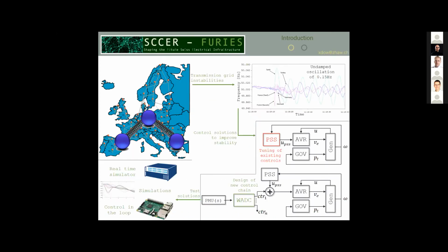Because of digitalization, industrialization, urbanization, the power consumption is growing every year. And this explains why the interconnection and the distances between generators are also increasing. However, more elements attached to the system implies that groups of generators can react adversely, causing the so-called inter-area oscillation. Inter-area oscillations are characterized by their low frequency, usually between 0.1 and 1 Hertz, and their low damping ratio.